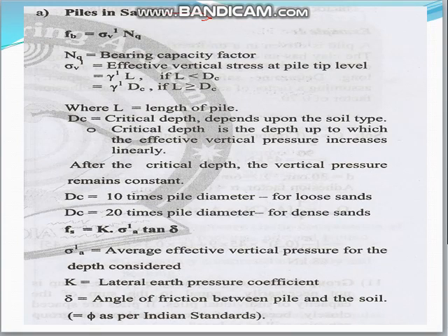I told you granular soils are nothing but gravel, sand and silt. For granular soils, the first one here, the bearing capacity at the pile tip, the terminology FB, is equal to the vertical stress at tip level into the bearing capacity factor.